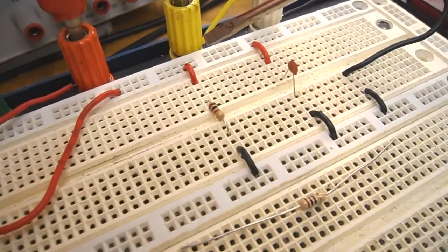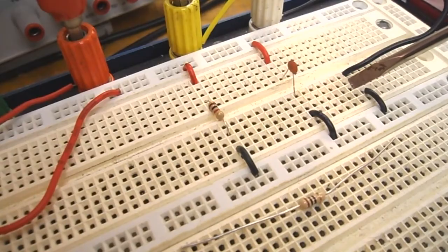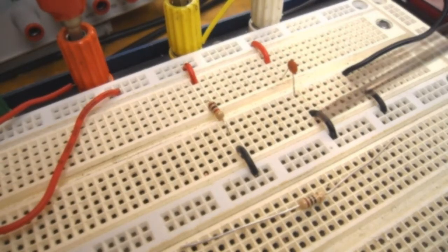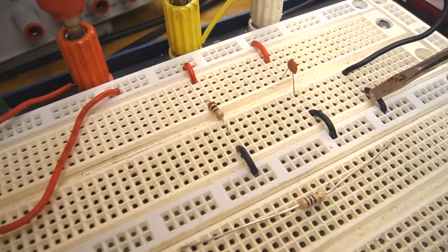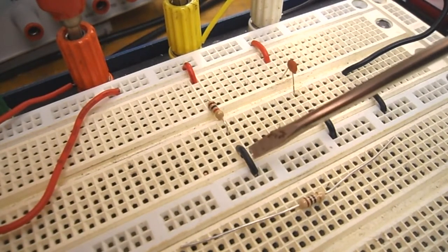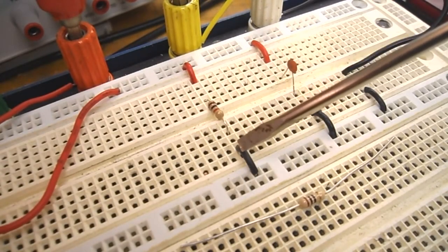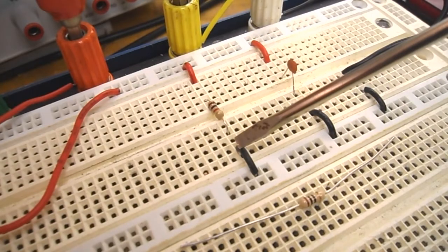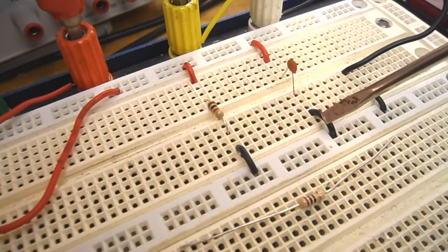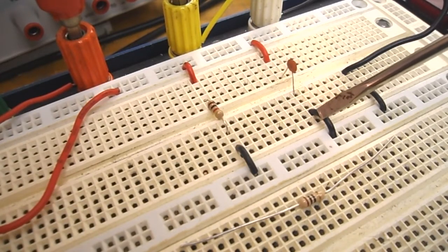So I'm going to take my yellow lead that goes to channel 2 of the oscilloscope, and I'm going to bring it over here to measure the total current. Then I'm going to take the 10 ohm resistor out and put it in series with the 1K ohm resistor, and I'll be able to measure the current going through the 1K ohm resistor. Then I'll take the 10 ohm resistor out and put it over here going through the 10 nanofarad capacitor, so I can see the current going through the 10 nanofarad capacitor. So I'll show you each step as I measure it.